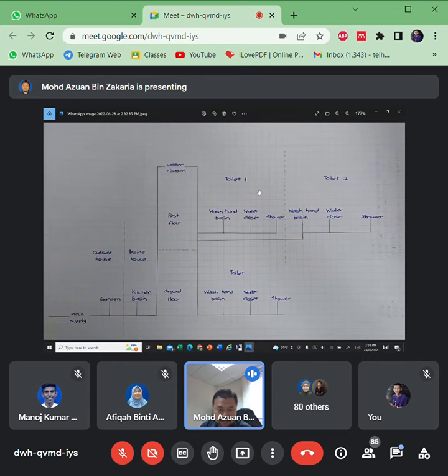Okay, so basically this schematic looks nice. Main supply, if possible there is a meter here. So this boundary is nice. The garden is inside. Okay, this is the same as the earlier case, you use the garden from direct water, which is not recommended. The garden should be from the water system. And then the kitchen basin is correct, and the rest is from the water system. So the first floor has all three, the second has all three, and the ground floor also has all three. So good, right? Good. Basically you can use this type of schematic, but this is also interesting.